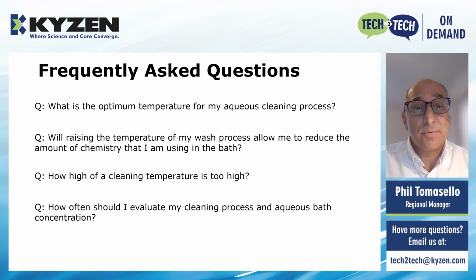Question number three, how high of a cleaning temperature is too high? And the answer is that, again, that depends upon the specifications that you have in the data sheets, the spec sheets provided on solder paste, on components, resistors, other substrates that you're using. But if you work with your analytical or your process lab, you'll be able to determine a range that is compatible for everything you're using.